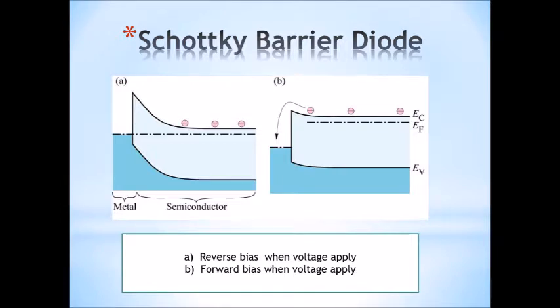If the applied voltage is greater than 0.2 volts, the free electrons gain enough energy to overcome the built-in voltage of the depletion region. As a result, electric current starts flowing through the Schottky diode. If the applied voltage is continuously increased, the depletion region becomes very thin and finally disappears.